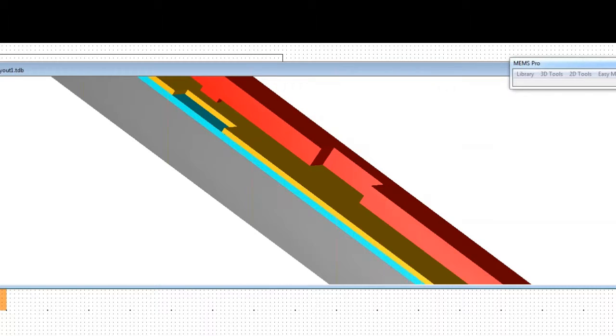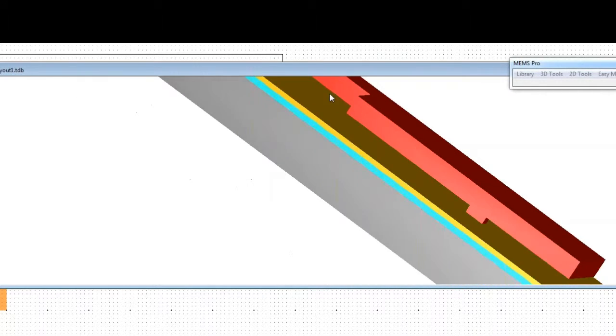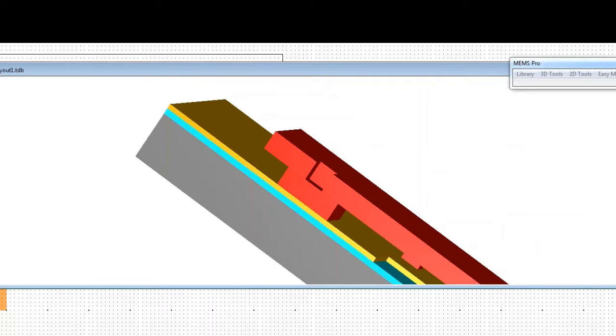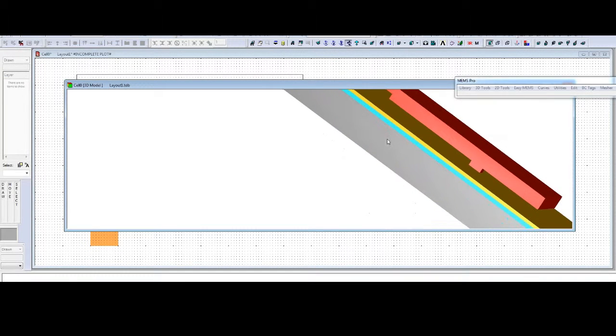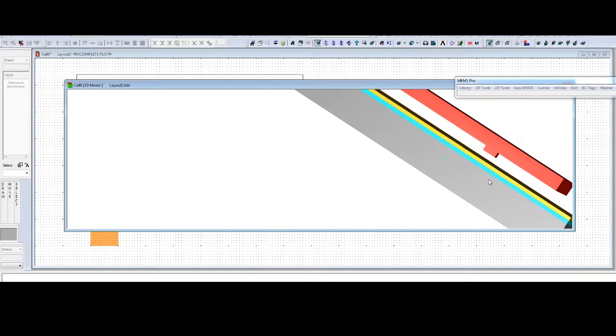But if you go, yeah? Use a dimple instead of an anchor? No, you wouldn't put a dimple on top of an anchor. That violates some design rules. No, I mean, can you use a dimple instead of using an anchor? No, you can't. And the reason you can't is, what's an anchor for? An anchor is to lock this thing down and anchor it to the previous layer so it doesn't float away. So if I use a dimple, there's no connection here.